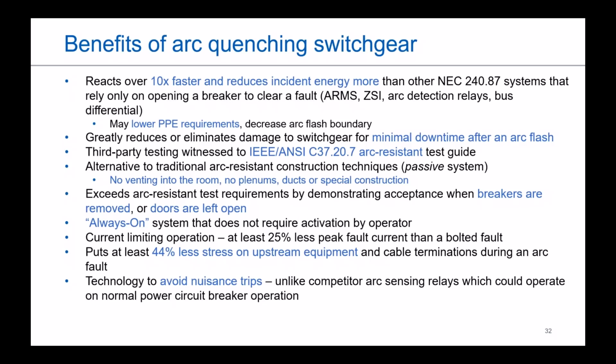If you have equipment in a high foot traffic area where a lot of folks are walking through, that's something to keep in consideration, because this is going to reduce where you have to lay out your boundaries on the floor for where somebody is allowed to walk. There's also the fact that it reduces the kind of damage you could potentially see within switchgear.